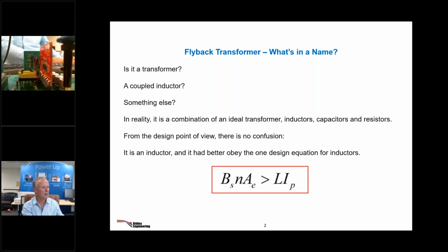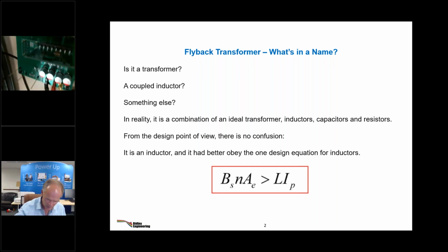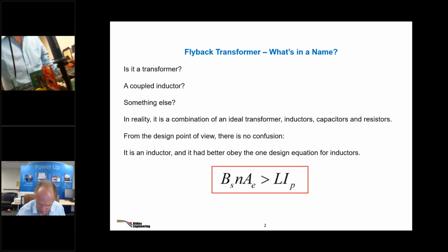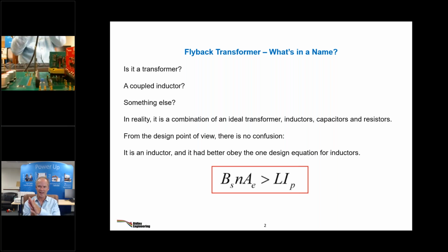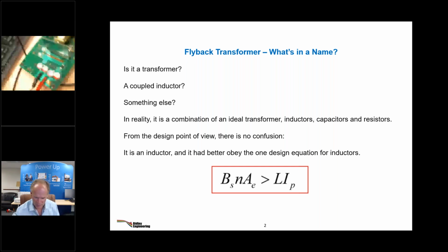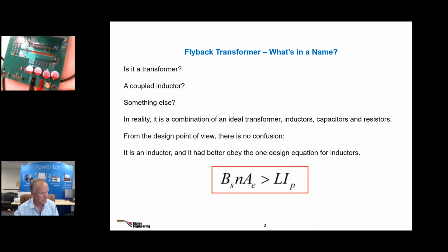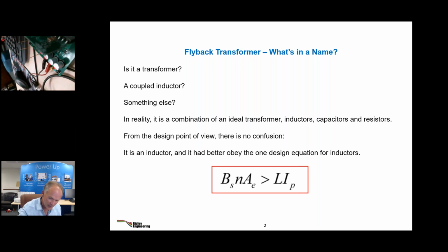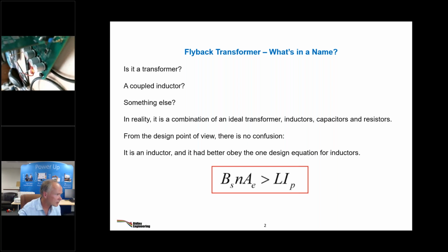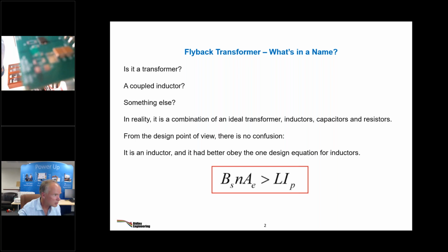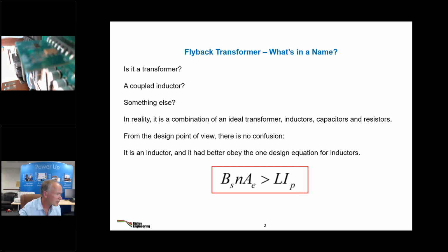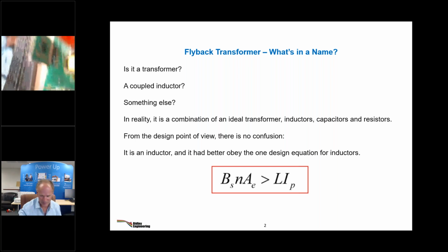All right, the cards add a fair amount of stray inductance. You're looking at our board layout, right? Tony Selsick asked that. So these cards, you've got things well spaced. It doesn't matter because the board layout is very tight. We're canceling everything when we go down to the board. Everything that's crucial is on the card. So bypass caps. Here on our board, we see the output caps, and then we see the diode rectifier card is here. They're separated by a long way. Hidden away on that diode rectifier card is a cap.